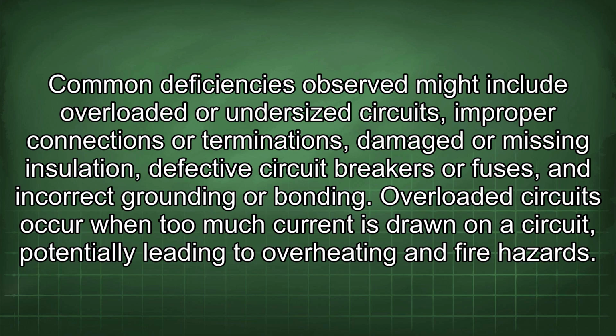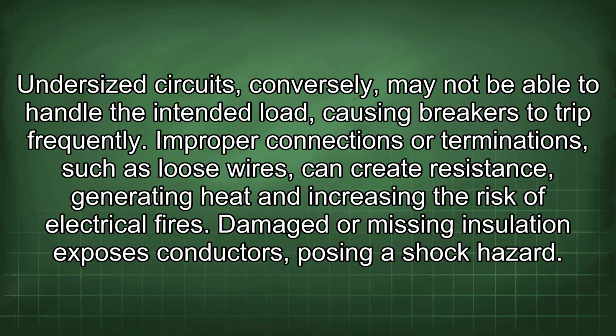Overloaded circuits occur when too much current is drawn on a circuit, potentially leading to overheating and fire hazards. Undersized circuits, conversely, may not be able to handle the intended load, causing breakers to trip frequently. Improper connections or terminations, such as loose wires, can create resistance, generating heat and increasing the risk of electrical fires.